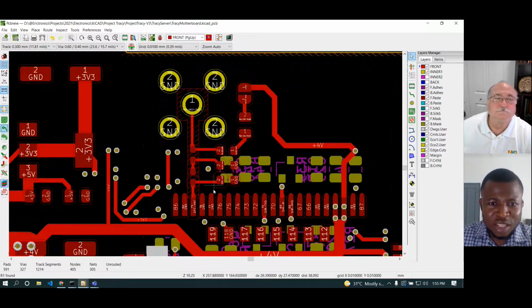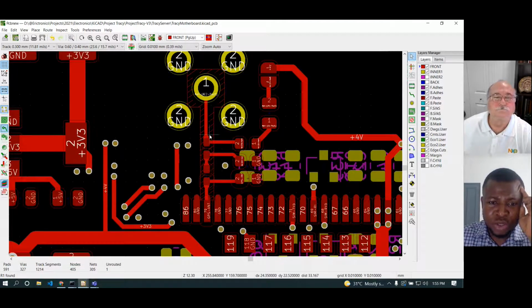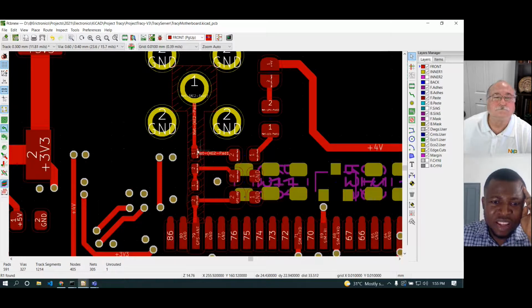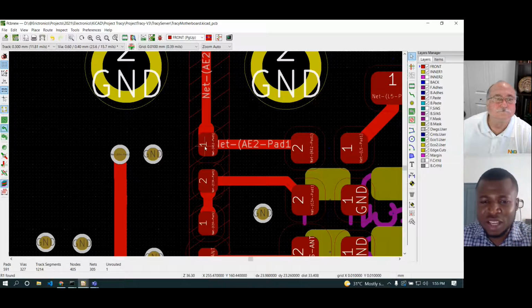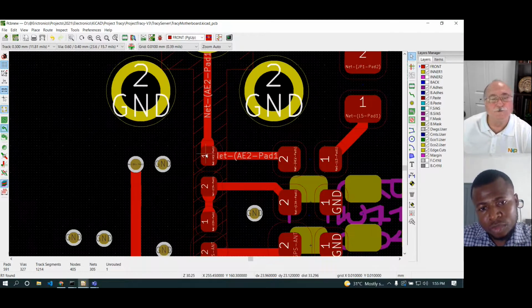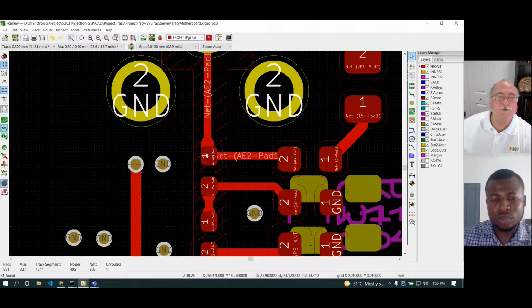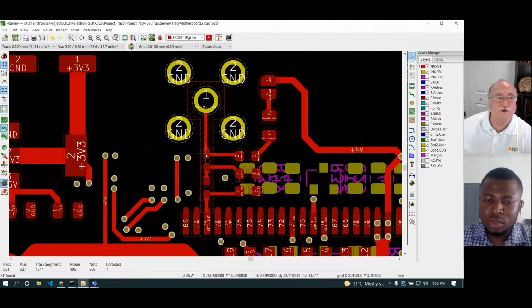So we have a GPS antenna, a 50 ohm impedance control line. But then I have to insert some capacitors in between. So I was wondering, this is supposed to be a 50 ohm impedance line, and when it meets the part of the capacitor, is there not going to be some reflection since there is a change in impedance? There always will be anytime the three-dimensional structure changes.